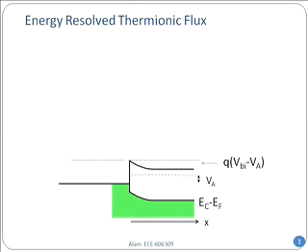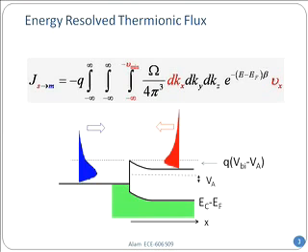Now in the last class, we looked at the two fluxes and calculated the current easily. Let's look at this in a little more detail so that you understand how these calculations proceed. This device has been forward biased because the semiconductor side is N, and the N side has been connected to the negative terminal of the battery. That's why the Fermi level has been pushed up. And the net barrier has gone down from VBI to VBI minus VA. VA is the applied bias. And you know these two fluxes. These red and the blue fluxes are of course going in both directions. But as far as I am interested in calculating the flux at the interface, I just take half of the fluxes that are going in the opposite direction. So generally you should really use a formula like this.